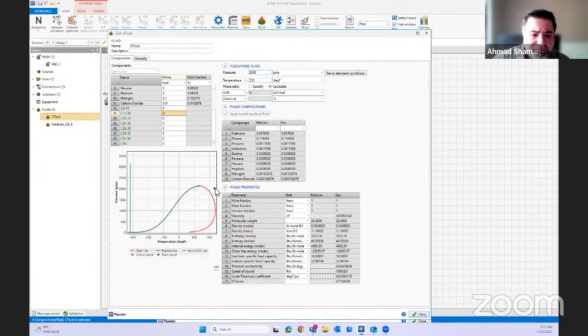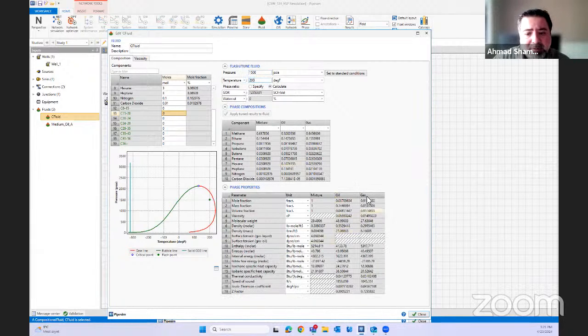Then we are here, okay? And now as the pressure goes down, we'll start entering, for example, if the pressure becomes 1500, then we are almost there. We are still gas, because we are on the right hand side. And then once we enter, because this is our critical point, if the temperature was let's say 200, then this is our gas fraction, this is our oil fraction.